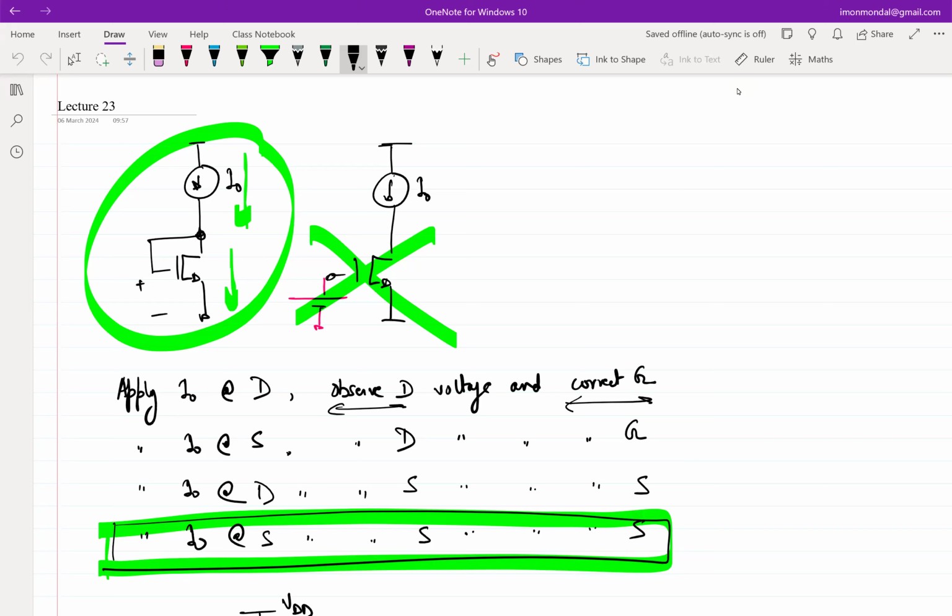essentially means that we kind of have two terminals from which we can observe if the transistor is able to provide an adequate amount of current to balance out the current source while keeping it in saturation, right? So essentially we had two terminals to apply current, and we also have two terminals to tweak the gate to source voltage, because ultimately gate to source voltage has to be tweaked automatically. You cannot have two independent sources which are independently trying to bias a transistor. Then it causes a problem.